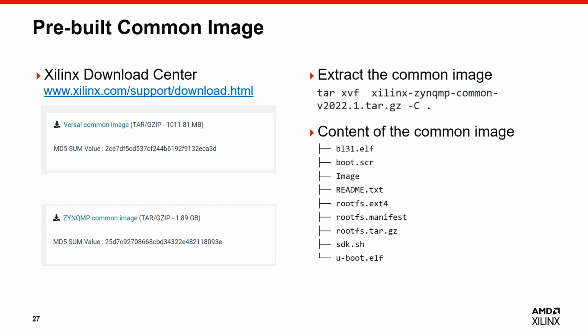Among the common images, bl31.elf is the trusted firmware. boot.scr is used by U-Boot to detect the boot device and boot from the corresponding device.